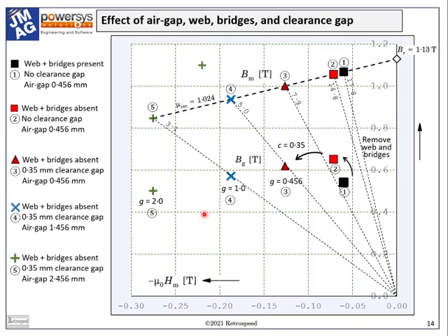This is the familiar demag curve of the magnet, showing the flux density, not the magnetization or polarization. And along the horizontal axis, the magnetizing force in amperes per meter multiplied by mu0, so that the units are essentially the same on both axes.